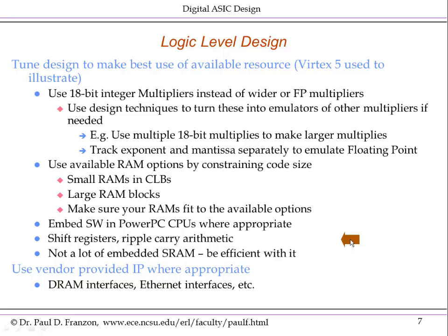If you have adders, you saw a ripple carry chain there. You didn't see a carry look ahead chain. So build your adders as ripple carry adders. We'll point out that the total amount of embedded SRAM available in many FPGA families is limited, so you want to be very careful and efficient in how you use it.